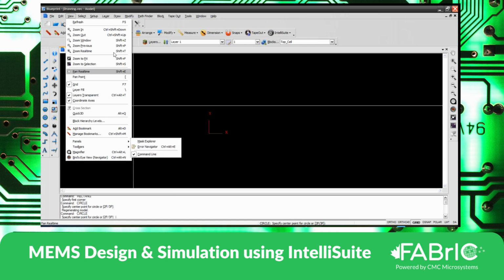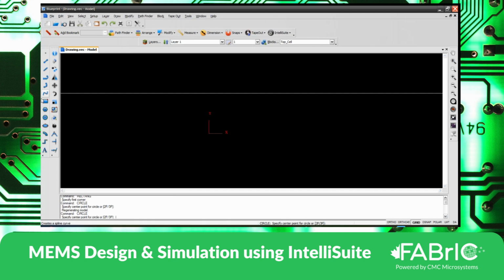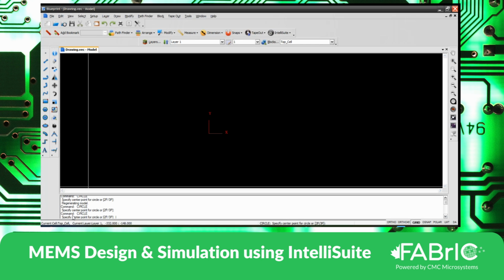Once this is done, when we click the geometry, you can see there is a message at the bottom: specify center point for 2P, 3P. So 0, 0. Press enter. That's the center point for a circle. What is the radius?